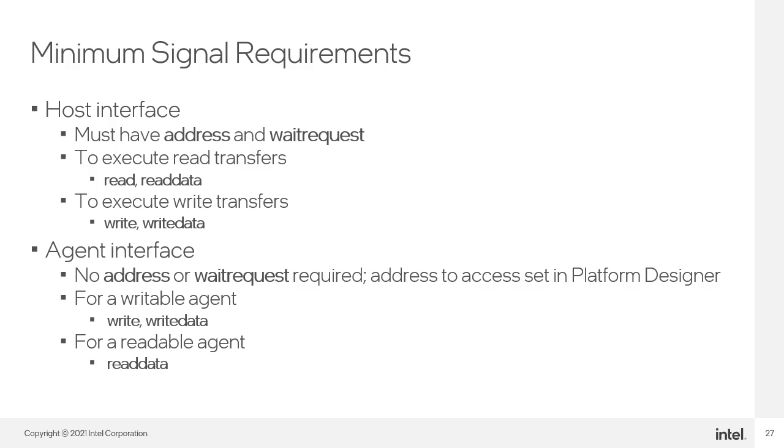To support write transfers, the write enable and write data signals are needed. For read transfers, only read data is required. With only read data, read transfers don't need to be qualified with an enable, so the agent will always return data pointed to by the specified address.